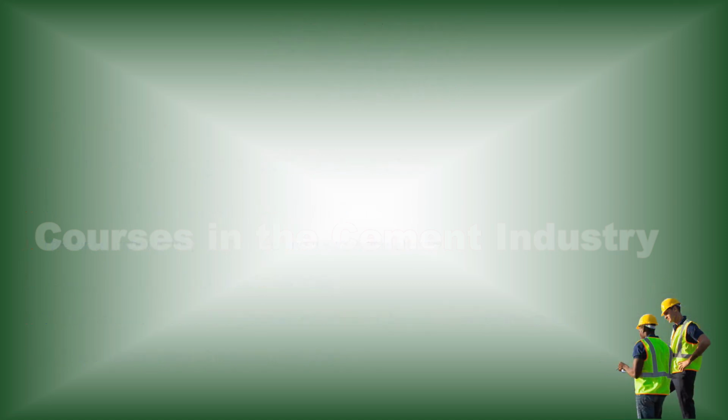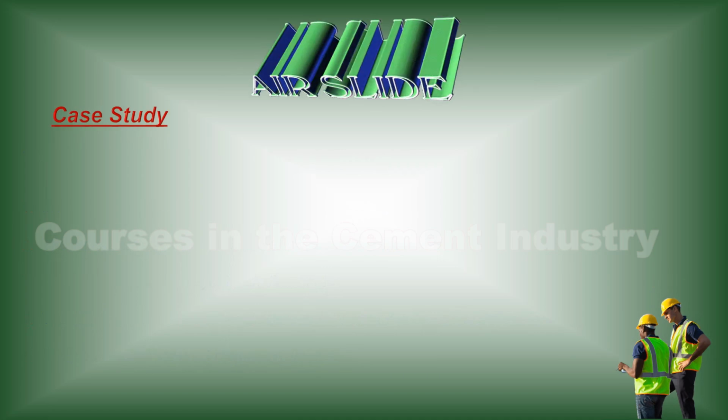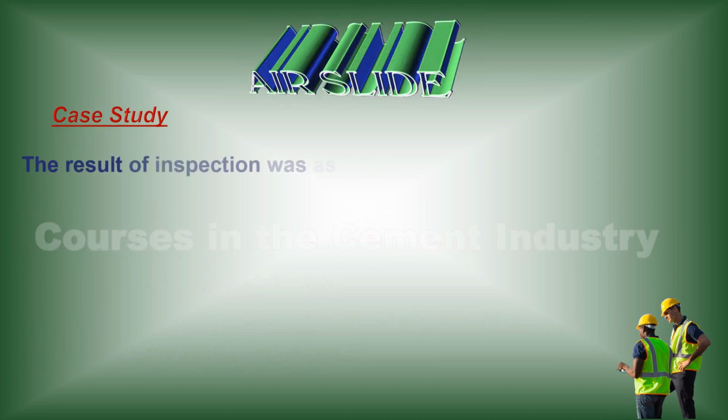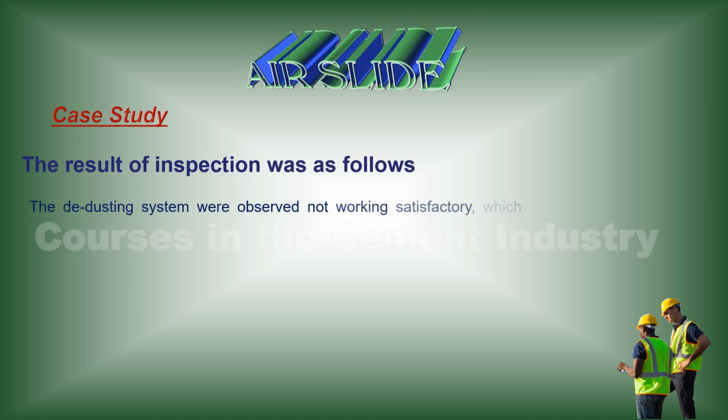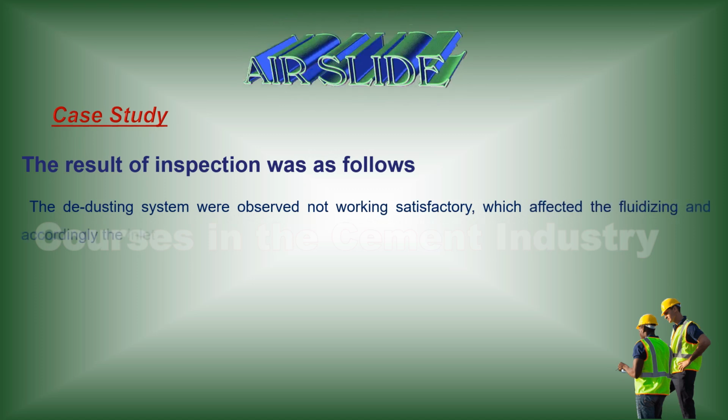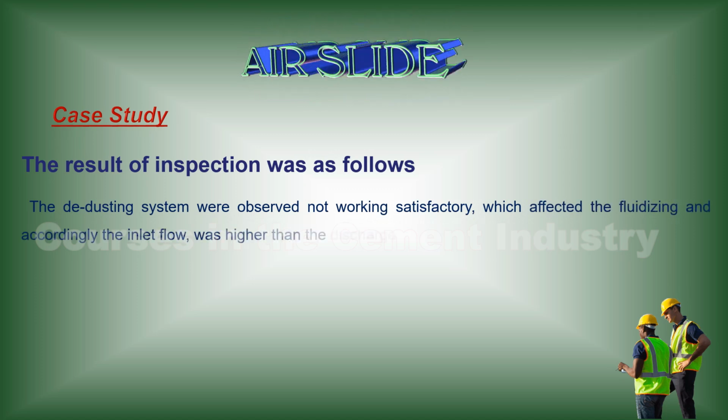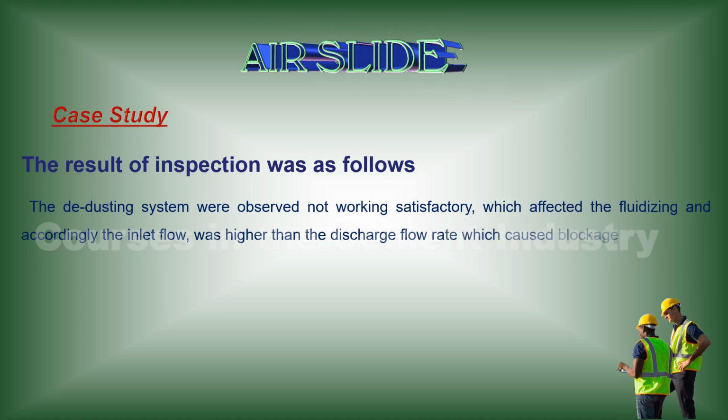We follow together, case study for air slide. The result of inspection was as follows. The dedusting system was observed not working satisfactorily, which affected the fluidizing, and accordingly the inlet flow was higher than the discharge flow rate, which caused blockage.